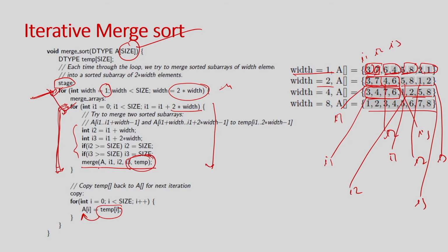Effectively you can see here there is a for loop here, there is a for loop here, and this merge also has a for loop, right. So, there are 3 nested for loops, and there is an array, this temp array. So, obviously the optimizations of the tool that will be relevant for this are unroll, loop pipeline and array partitioning,